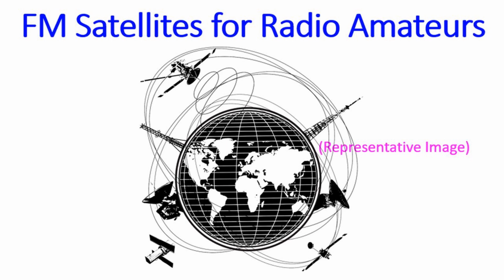For example, the beam width is important in LEO satellite operations. An antenna with a wider beam width is easier to point at a fast-moving satellite for a beginner, while one with higher gain and directivity but having narrower beam width will be more difficult to point exactly.